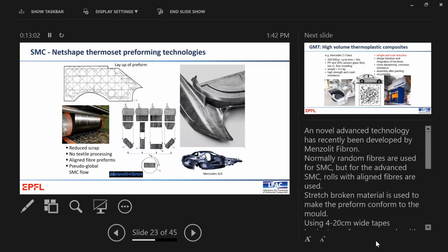It's widely known. And people have gone on to use carbon fiber SMC, where they've made some kind of UD material with some random fiber inside, which can be placed into near net shape preforms. And then you can pressure mold these in under a minute, a 90 second cycle time. So you can push these out at high volumes. You can make lots and lots of them. So they're good for mass adoption. And this gives you a lot more weight saving than the glass material. And you can use slightly better resins, vinyl esters, epoxies, rather than polyesters. So very interesting material, and I think we'll see more of it in automotive.